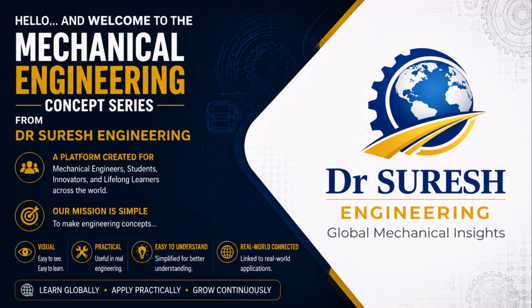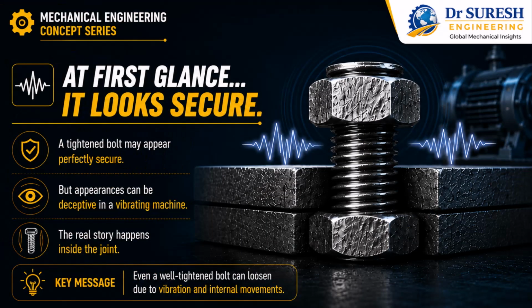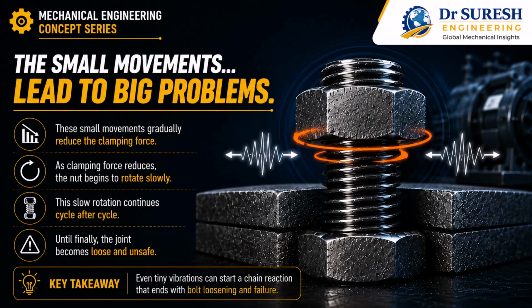In today's session, we explore one of the most common yet most misunderstood problems in machine design. Why do bolts loosen even after proper tightening? At first glance, a tightened bolt may appear perfectly secure, but inside a vibrating machine, tiny motions begin to develop. These small movements gradually reduce the clamping force, causing the nut to rotate slowly until the joint eventually becomes loose.